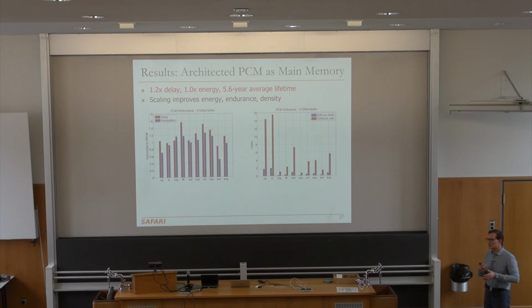Well, you could argue that if you actually scale, that improves energy, that improves endurance, that definitely improves density, hopefully, but that's not clear also. Well, at least endurance and energy are not fully clear, but latency doesn't improve, for example. Okay, so there are many caveats here. One is worst case lifetime is much shorter. If you look over here, for some very memory intensive, write intensive applications, they still destroy your memory very quickly. This is about 1 year, right? If you look over here, it's actually less than 1 year. Even if you do these writes at a smaller granularity than the row granularity.